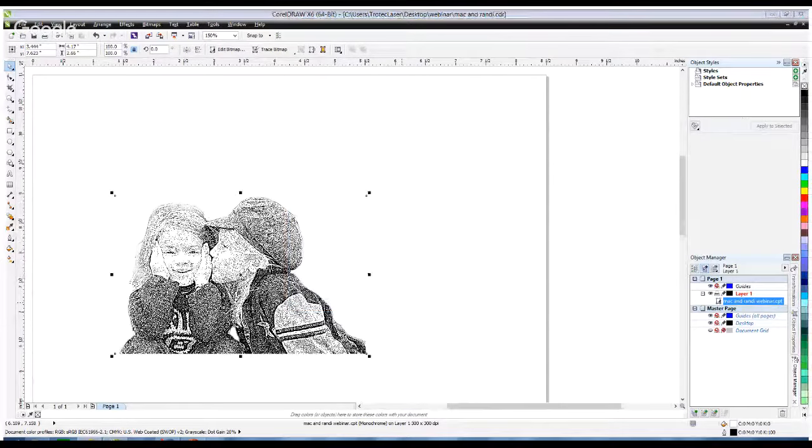I'm going to go to preferences. I'm working with basically a 4.5-inch image by 2.75. I'm going to set my power and speed here. Again, 70 power, 100 speed. Again, I'm using 120 watt lasers, so I'm not even using the full amount of power, but I am running as fast as I can.